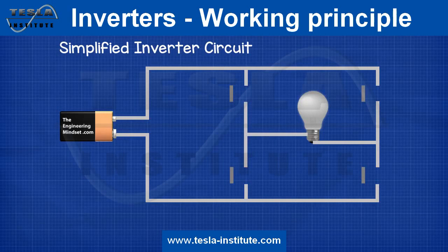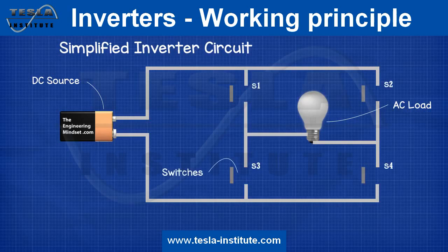Well, let's consider a simplified circuit where the DC source is being used to power an AC load, represented by the lamp. To convert the DC to AC, we will use 4 switches. We will pair the switches together so that switches 2 and 3 open when 1 and 4 close, and vice versa. This will allow us to force the current through the AC load in an alternating direction so that the lamp will experience an alternating current even though it's from a DC source.